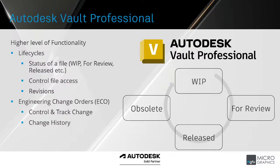So here we can control and track changes that are being requested and that are being active within Vault. So that would allow a user to take part from an assembly or a design from released back to work in progress and track that change history, and also track changes in revision. We're now going into a revision A or a revision B of that file.